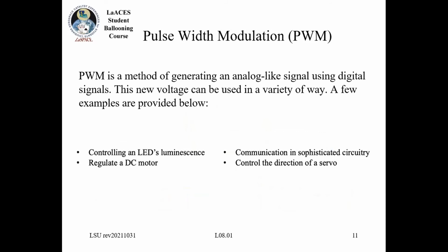All right. So now, what about this pulse width modulation, right? And I may have mentioned this previously, it gives you this sort of quasi-analog signal. And this is how you're going to do stuff like control motors or control the position of a servo. So it's not really an analog signal because it is a digital signal, but it gives you a way to have a continuously varying value.